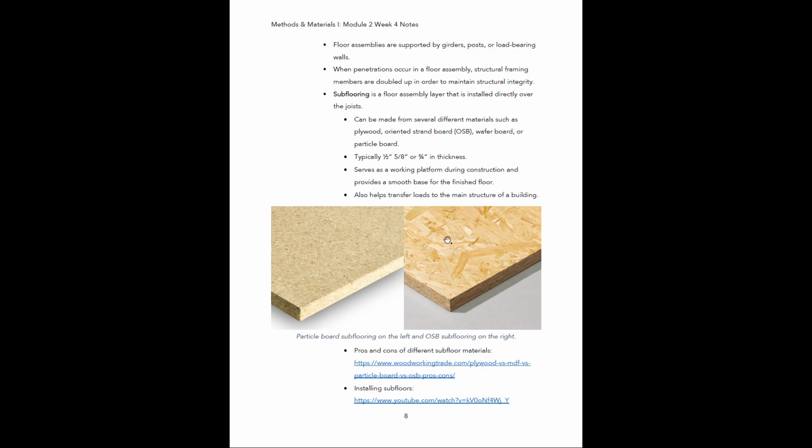So when you compare it to something like OSB or plywood, it's usually a lot weaker, and because of that, it can't really hold nails very well. If you try to nail or screw into this, it has a tendency to just break apart because it's really brittle. And also, if it gets wet, it's the end. If this stuff gets wet, it basically disintegrates. It's not very great. It's not used very often, but it's a lot cheaper.